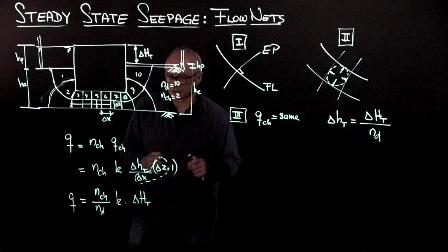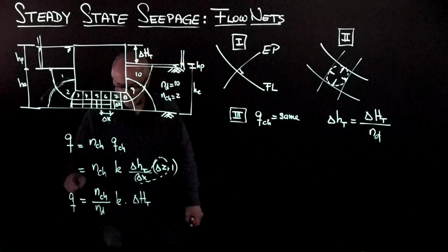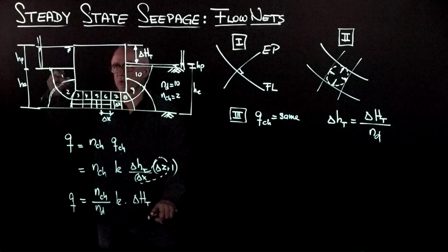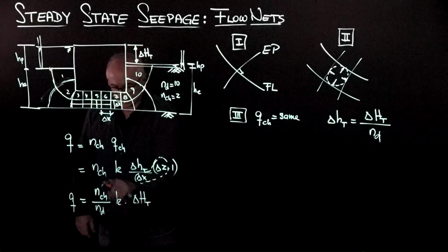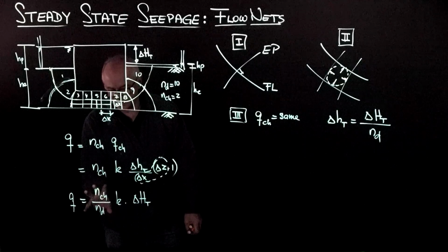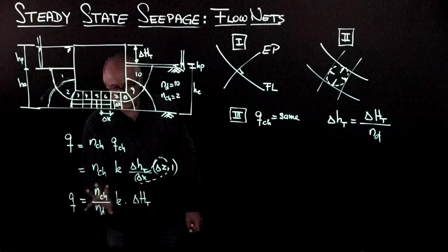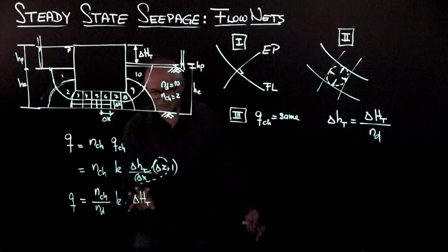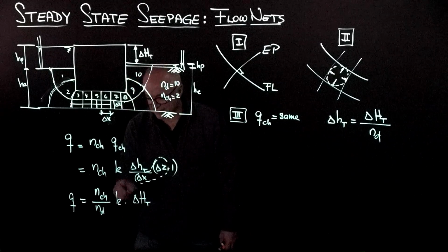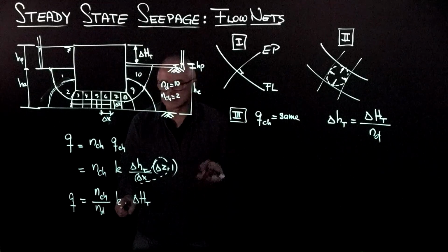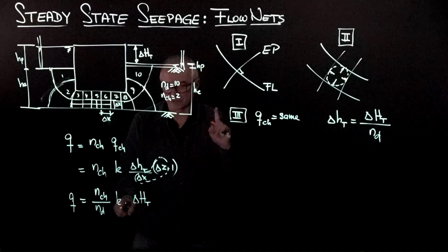One more observation, particularly if you are thinking about flow rate: the total change in energy is very well known because your problem gives it to you. This is a function of the geometry of the problem, and it's going to be very stable. So very limited uncertainty here, even if you do it with a flow net that you sketch in 2 minutes. No uncertainty here because this is a constraint of the engineering design. Now, here is the problem. This one, K, varies in orders of magnitude with an uncertainty of plus or minus 1 order of magnitude.